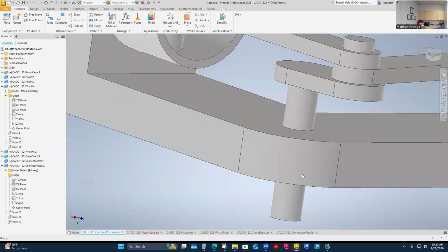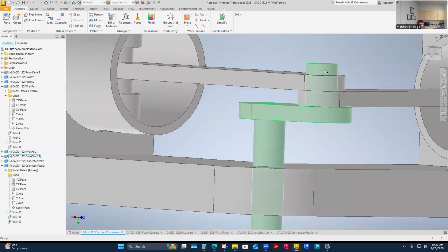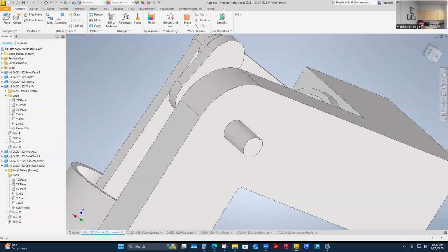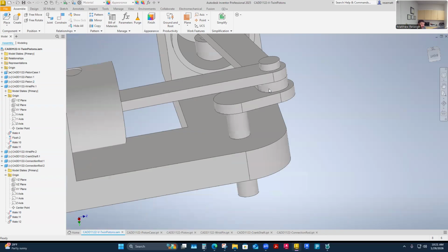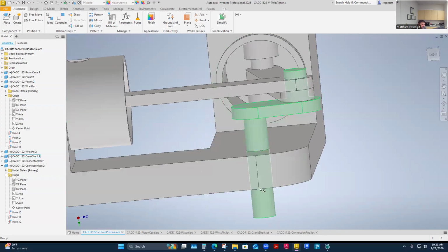So I'm going to put a snap ring here and here to hold that thing in alignment, and then a keeper to keep those two together so they don't fall off. And then I need the same for through here. And then eventually I want to be able to just turn it here, like when it's on my table as my fidget toy. You could make this where you turn it from the top side, but you would still have to kind of pin through here for stability.